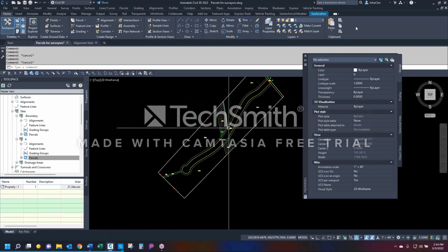Good. Now, I'm bringing this up because there is a hierarchy to parcels. Feature lines usually have a hierarchy, and we're going to start with that discussion. Whatever was drawn last in the feature line will rule, or however the feature lines are set up in their hierarchy will rule. Depends on how it was done. Generally, from the initial setup, this is the hierarchy, the style of the feature line. Style on top rules over the styles below. Then you draw in your feature lines, and whatever was drawn last, regardless of what style it was, all of a sudden becomes the ruler. It's kind of weird. But parcels are not like that in any way, shape, or form.